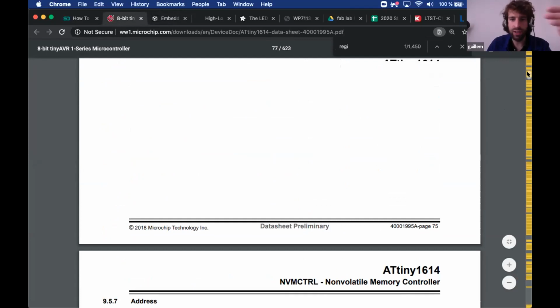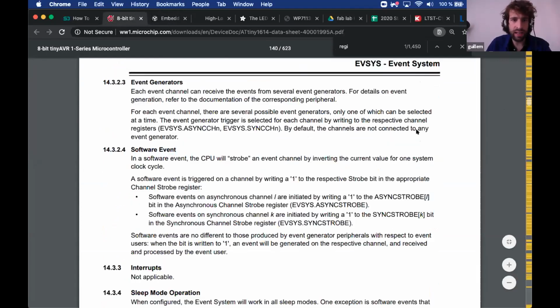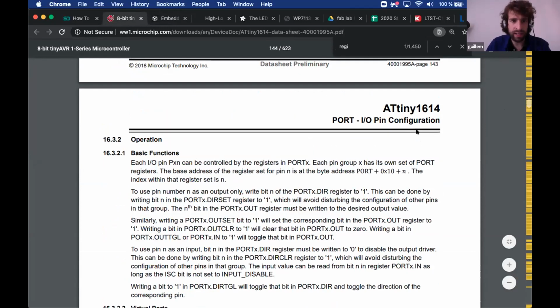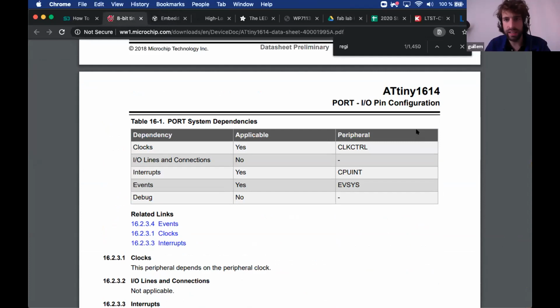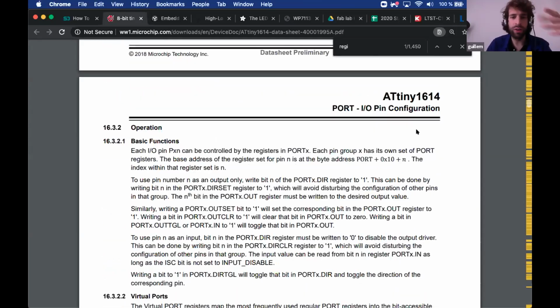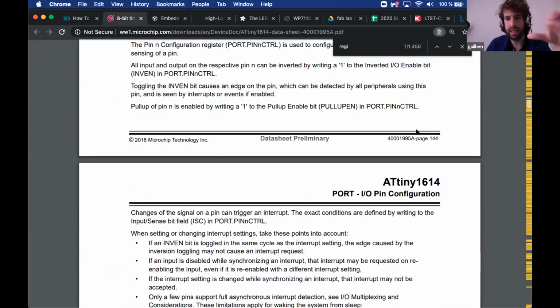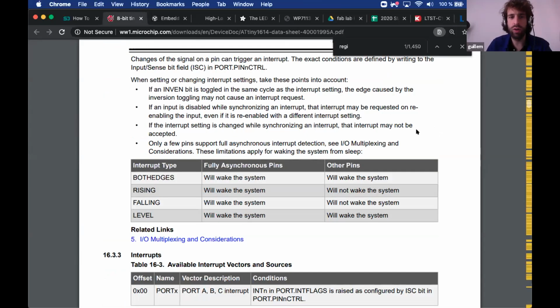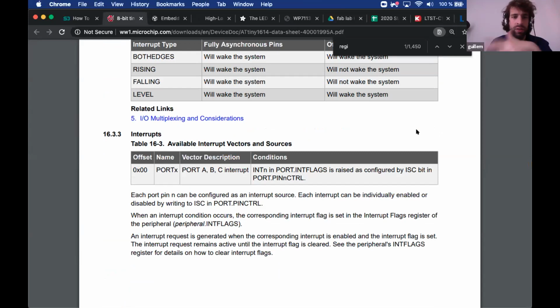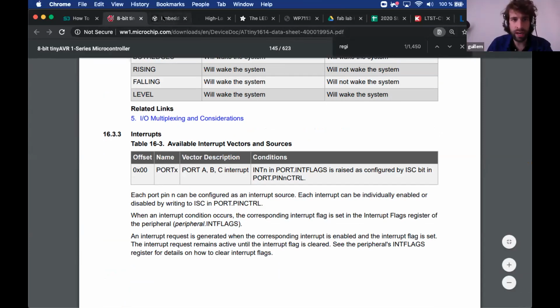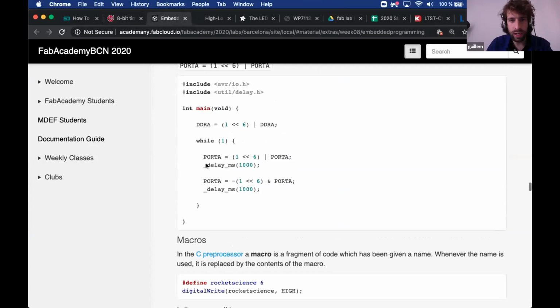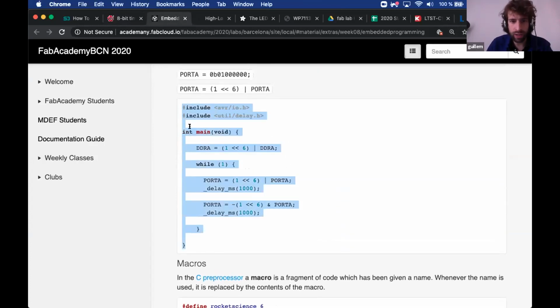However, as switches could be quite complex to turn on and off, it's easier that we use libraries that simplify this, such as Arduino, where by simply doing a digital write or a digital read, we can execute all this complexity. So at the end, when we think about Arduino or other libraries to program microcontrollers, what you are looking at is simply an abstraction of all these pages into code. Now we are talking to code instead of reading code and implementing things ourselves. And why do people keep implementing things directly instead of in the Arduino language? If you look at some new code, it might look more like what I'm showing you now on screen, working directly with the registers, working directly with the memory, because this is extremely efficient and extremely precise on time.